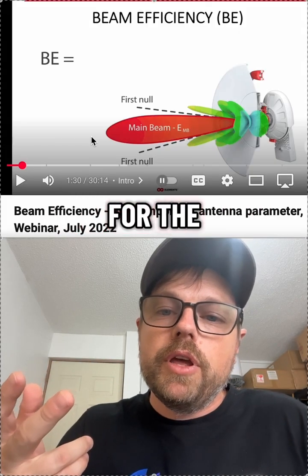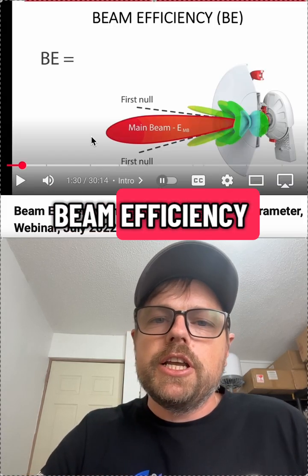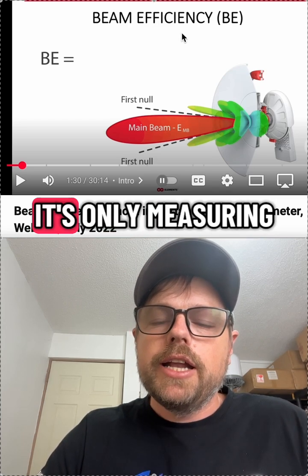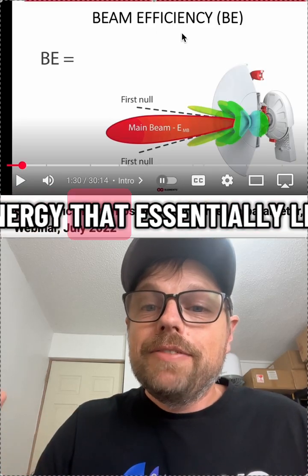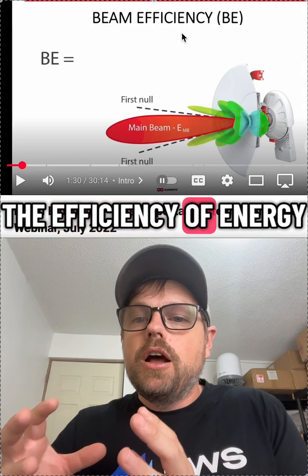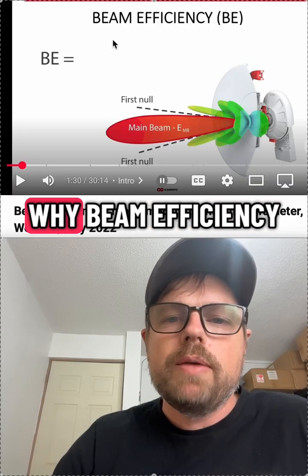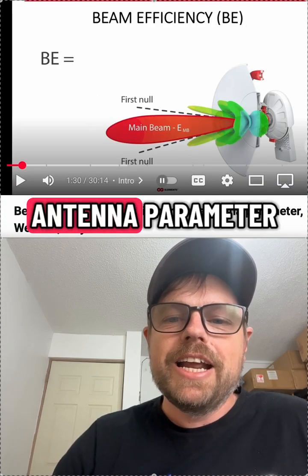It will account for the loss of energy by the radome. Beam efficiency, although it's called efficiency, it's not measuring antenna efficiency. It's only measuring the energy that essentially leaves the antenna. It's not talking about any of the efficiency of energy before the signal leaves the antenna. And that's one reason why beam efficiency is really an incomplete antenna parameter.